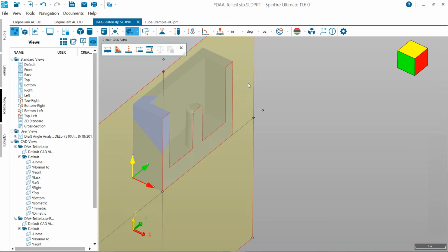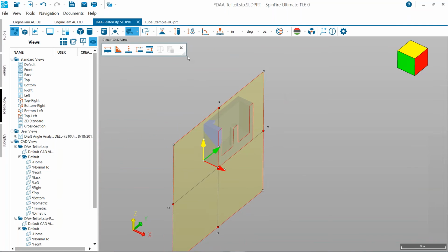It's possible it's just the tessellation because of the extreme curvature of that when you do a section cut, because it was brought in with standard tessellation. You just may need to increase that. Just like a CAD system has its own tolerance, we do as well. 99% of the cases it's fine, but every once in a while you'll find that type of thin wall example that you may need to increase that.